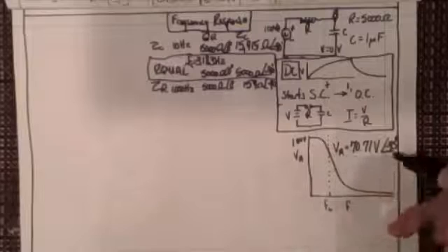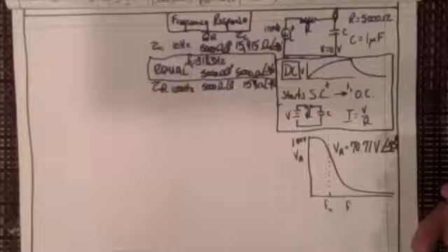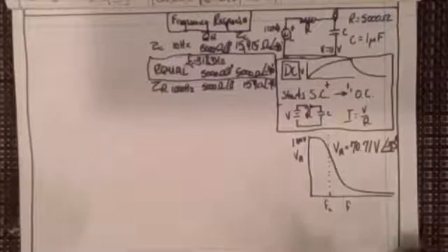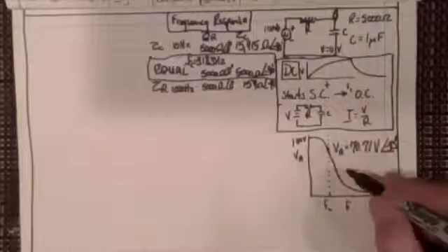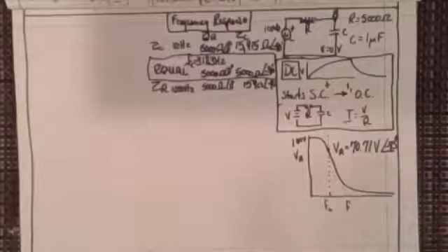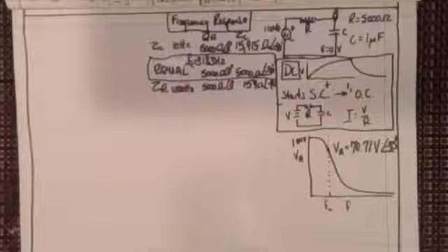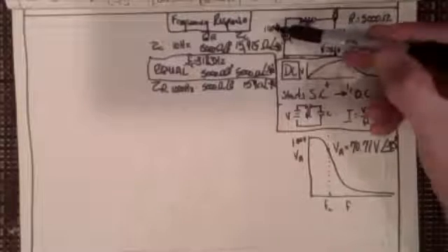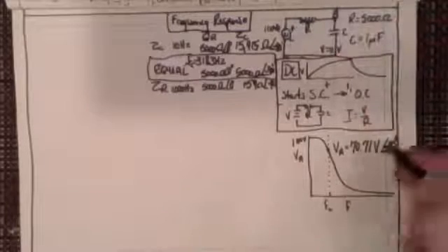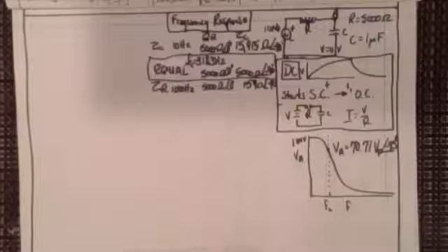voltage is. Now, that voltage is very special, by the way. I don't know if I want to get off track here right now, but this voltage with a 70.71, of course, you know that that's 1 over the square root of 2 times the source voltage, which is 100 volts peak, right? So this is still volts peak that I'm talking about here. It's not RMS.